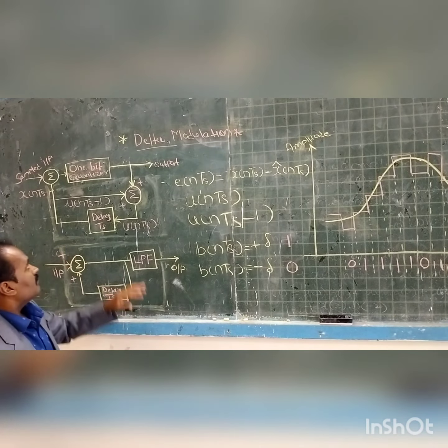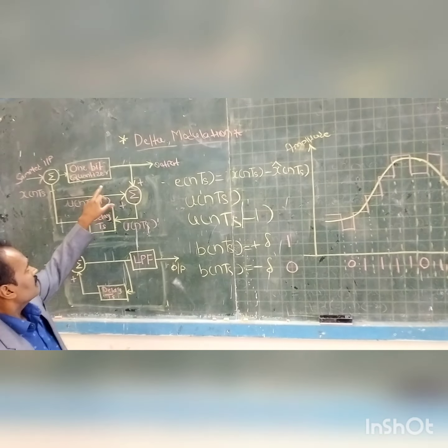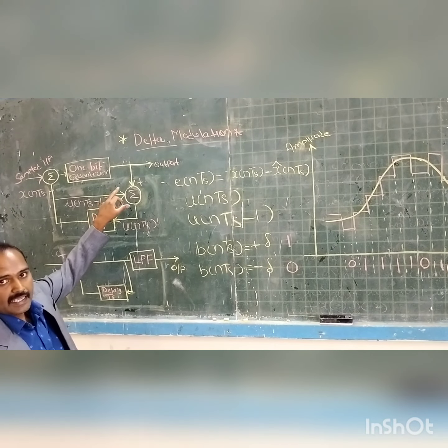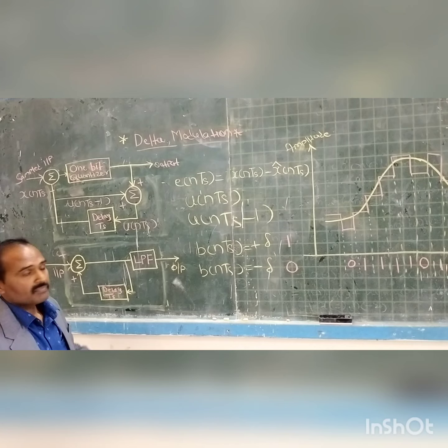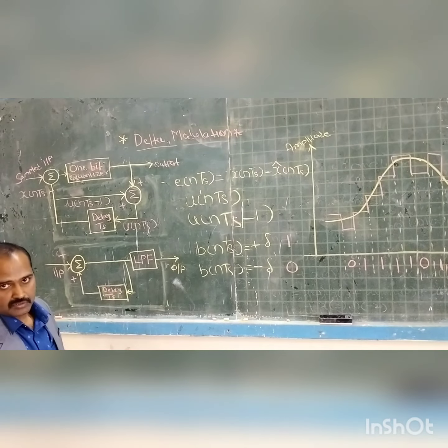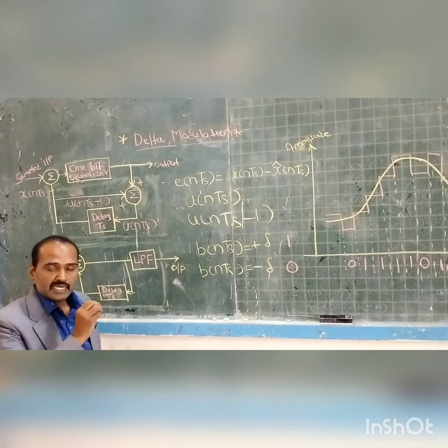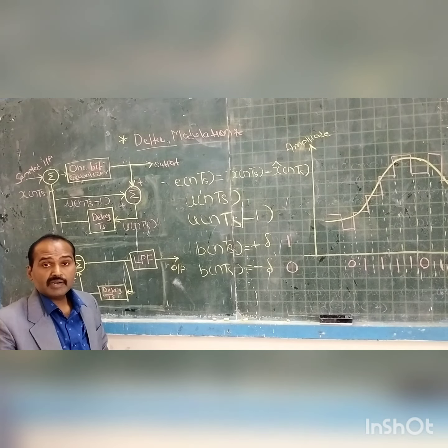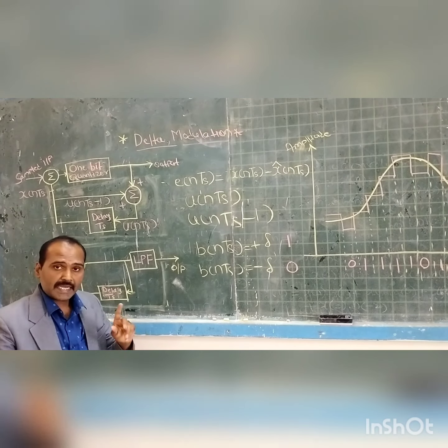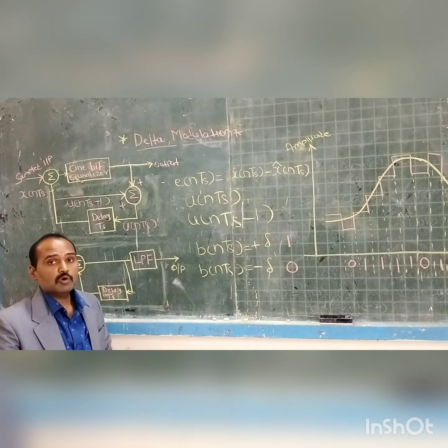And these are the desired waveforms, and we have some mathematical treatment belonging to this delta modulation scheme, right? So as far as this delta modulator is concerned, as you can see in this transmitter block diagram, we are having n number of finite blocks with us, right? This delta modulator can be called a one bit quantizer. That is the unique identity of this delta modulation scheme.